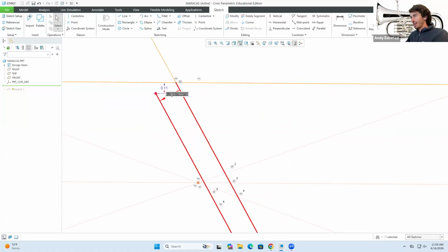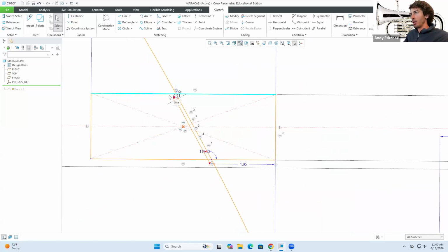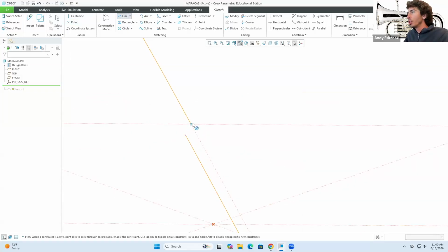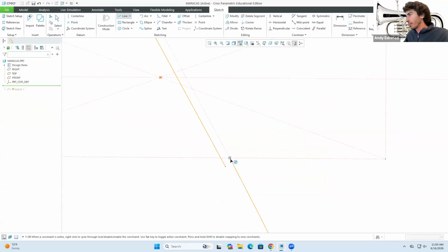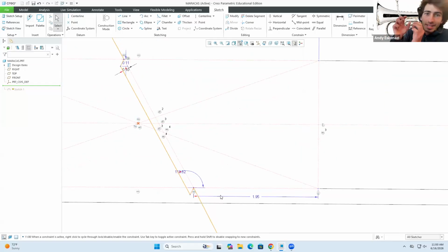And that offset, in reality, I want that to be 0.1. Like nothing too crazy. And now, so that line that I just drew, I'll make it construction, while all of these other lines, I'll also make them construction. So now what we're left with doing is connecting that point and that point, that point and that point. And there you will have like a little extrusion from where you can, for instance, do a cut. Like this is one approach.